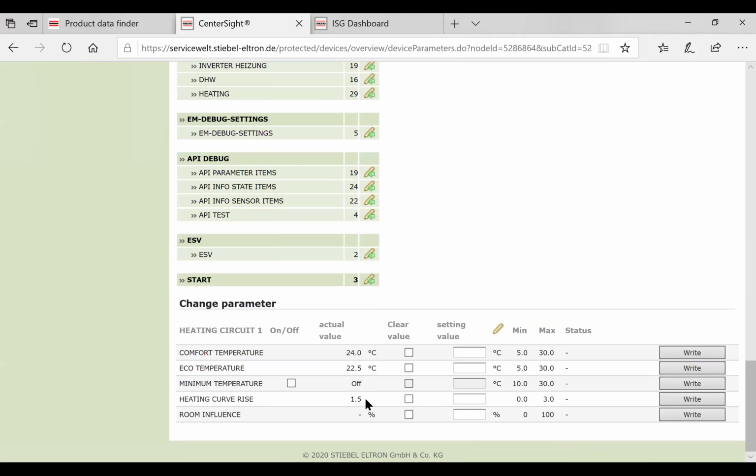We've obviously done this because it's a big open area with massive glass, so therefore it's incredibly inefficient. We've put a high heat curve there because, walking in there, the main thing is seeing a warm floor and seeing the thing operating. They want to be able to turn that unit on and have it operate so people can see it going, so I punched in a high heat curve and a high comfort temperature. But normally, underfloor heating, very well built house, 0.6 to 0.8, and radiators or something, maybe 1.8 to 2.